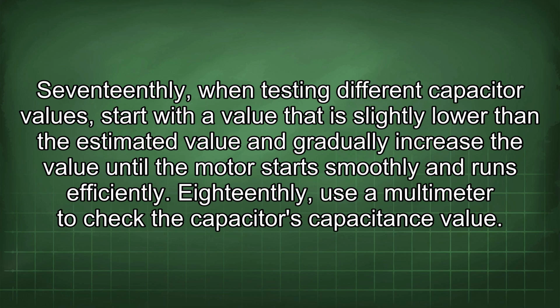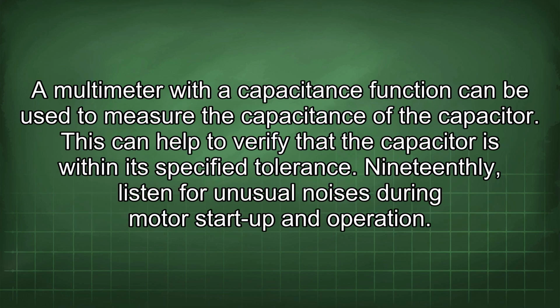18th, use a multimeter to check the capacitor's capacitance value. A multimeter with a capacitance function can be used to measure the capacitance of the capacitor. This can help to verify that the capacitor is within its specified tolerance.